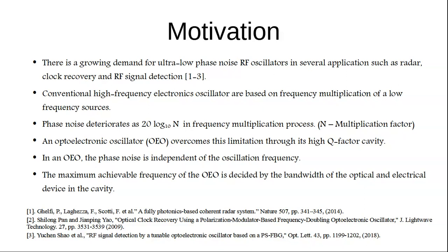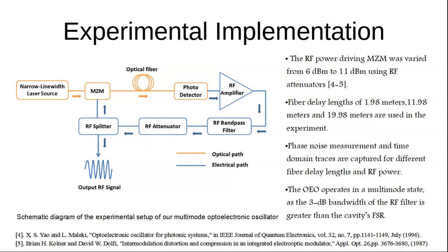An optoelectronic oscillator overcomes this limitation through its high Q factor cavity. In an OEO, the phase noise is independent of the oscillation frequency as well. The maximum achievable frequency of the OEO is decided by the bandwidth of the optical and electrical devices in the cavity. The experimental setup of our OEO is shown here.